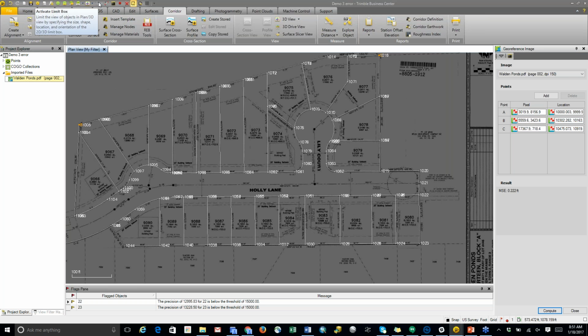So a few more questions, and then we'll kind of move on. Joe asked, does the COGO tool use grid bearing or true bearing? And I believe it uses grid bearing. When you say true bearing, are you talking about like a plan bearing or something like that? Maybe elaborate a little bit more what you mean by true bearing. Based off true north. Based off true north, and that deflection between true north and grid north. That conversion thing. Yeah. Okay, perfect. That's what I'm assuming you're talking about. Yeah, no, so right now in this version of TBC, you have to figure out what that difference is, or that angle between plan angle and grid angle, and then